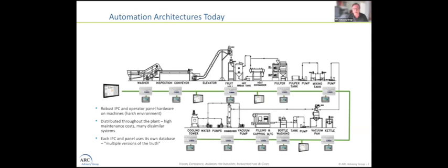Typically, we equip each machine, each station with its own PLC and its own operator panel so that somebody can stand there, can set parameters on the machine, operate it, can read values from the machine, can monitor to make sure that the process is proceeding smoothly, and can quickly identify faults that are reported locally if anything happens.